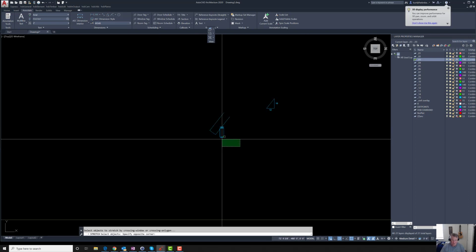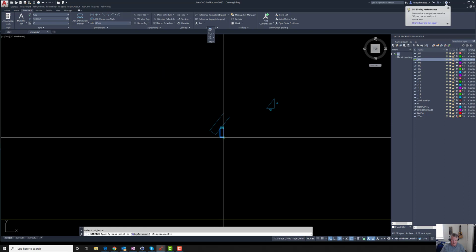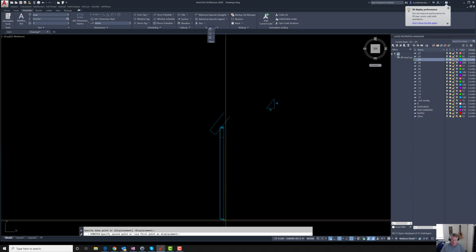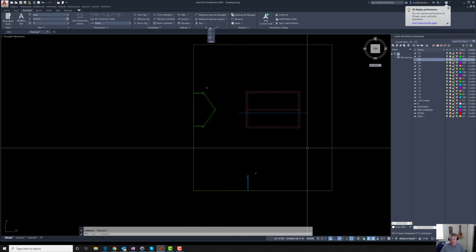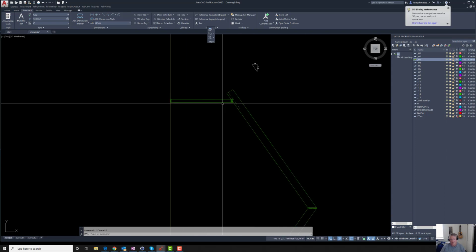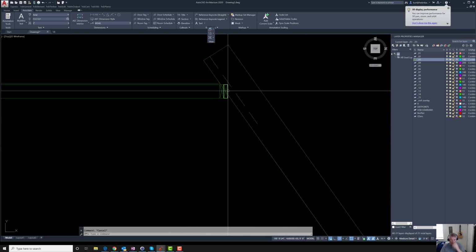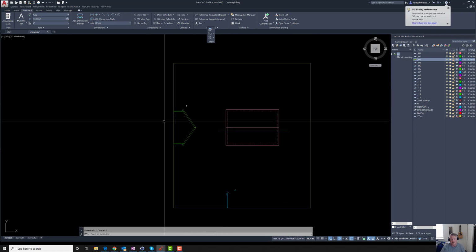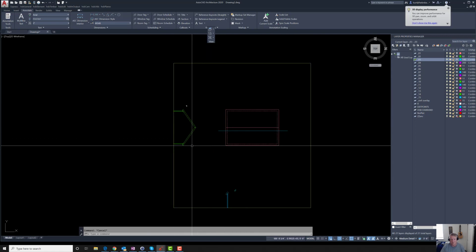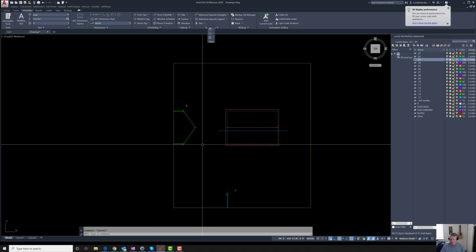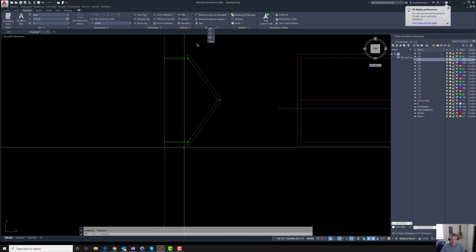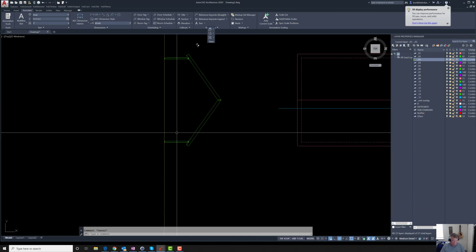I will stretch again the plate down to the bottom, and this is one of the reasons I use this method: now to get the height of wall consistent all the way around, assuming that, on the first attempt, we're going to use a consistent wall height for the entire thing at 8 foot 0 3/4.